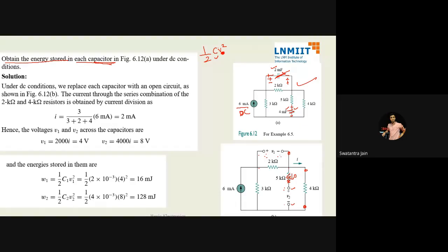We are removing the capacitor considering that it has charged fully, right? Yes, because DC values always mean t is equal to infinity. T equal to infinity signifies that all the fluctuation in my voltage or current values has settled down. That is also called steady state. In steady state, the capacitor gets charged fully and the voltage is constant.